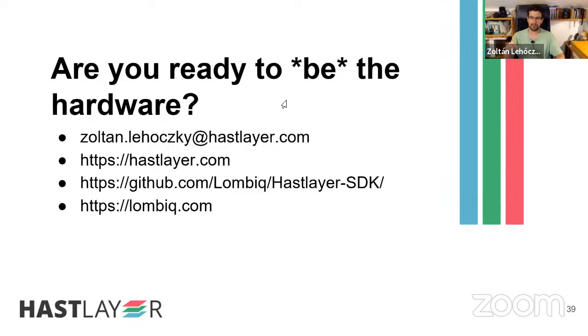In the particular case of what I've shown you, the CPU is actually something around 800 megahertz, and again, it's an ARM CPU for embedded devices, and the FPGA was around 150 megahertz or so. So while the FPGA is a lot more efficient per clock cycle, it also has a lot fewer clock cycles. It depends. The best way is to try.